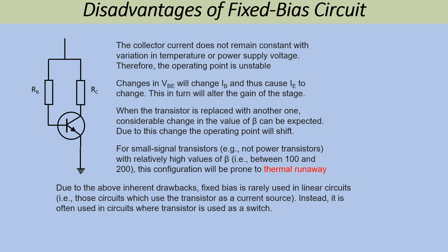Due to the above, this fixed bias arrangement is rarely used in linear circuits. And linear circuits, by the way, are those circuits in which the transistor acts as a current source. However, you can use this fixed bias arrangement when you wish to use transistors as switches.